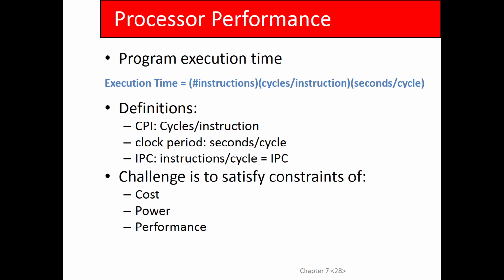So nowadays, memory is cheap, so let's not worry so much about this, and let's try to get the number of cycles per instruction as low as possible. These days you end up with instruction sets that are very wordy and execute a lot of instructions, but each individual instruction is really fast. So this term is lower.